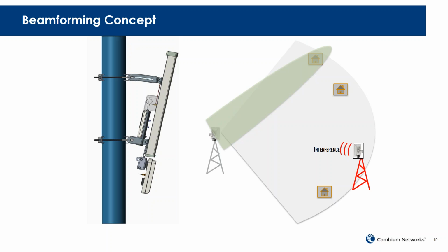And each of the beams has the effect of increasing the gain to our desired location and at the same time attenuating the signal for anything else it receives. And in this example, the interference is attenuated while the signal is increased, which improves signal to noise ratio. And that's what we talked about. Anything we can do to increase the signal, anything we can do to decrease the noise, beamforming does both of those things.